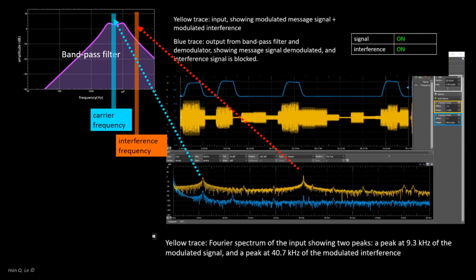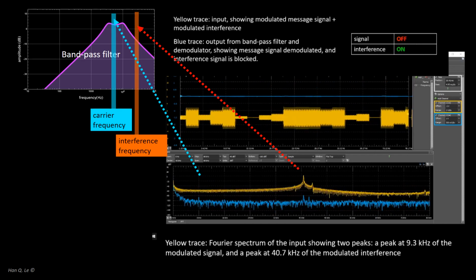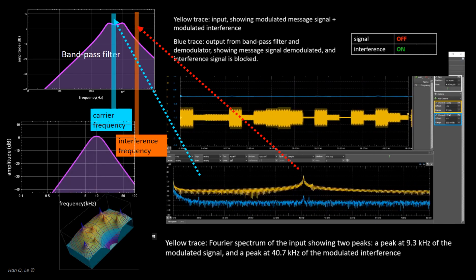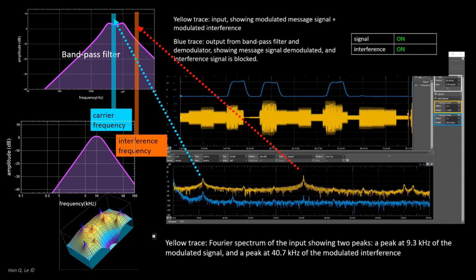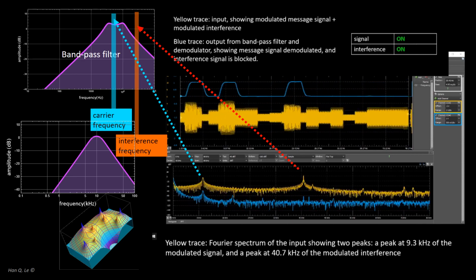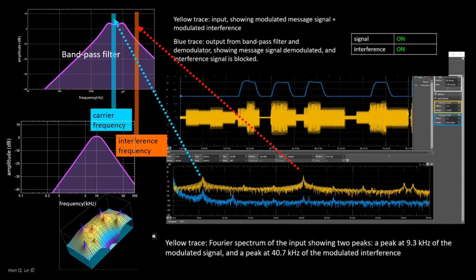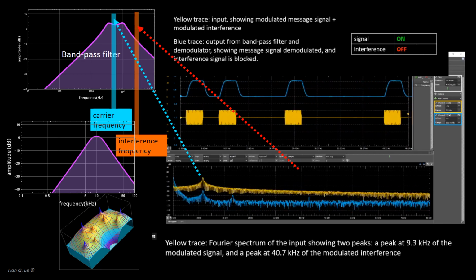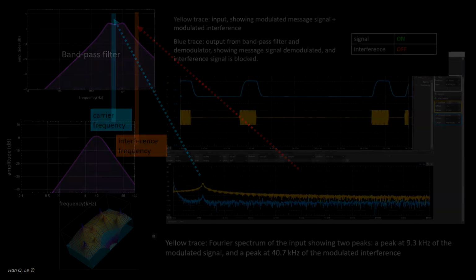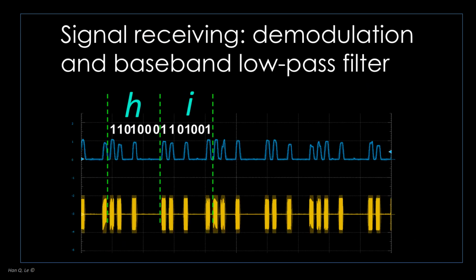Part of the problem is that this filter is not sharp enough. Shown here was another project for a different class which uses a fourth-order, 8-pole filter that offers higher out-of-band rejection. The more discriminating a filter is, the less noise power can get through, and the better is the signal quality. This is the end result, the retrieval of the original message.